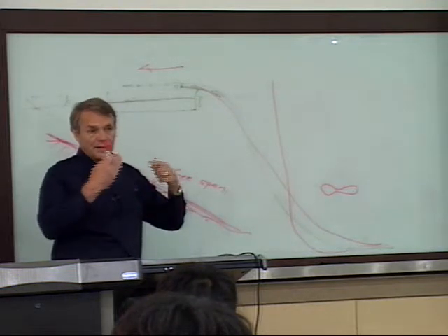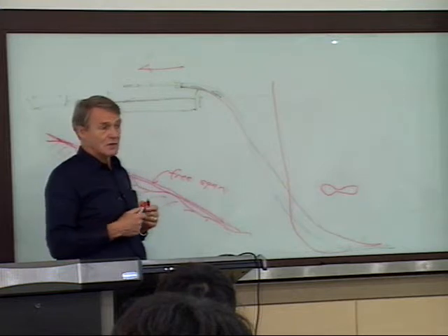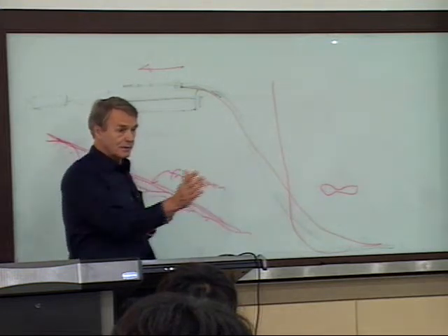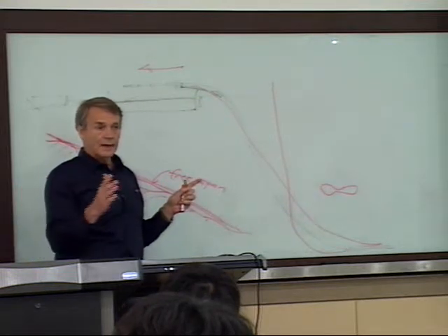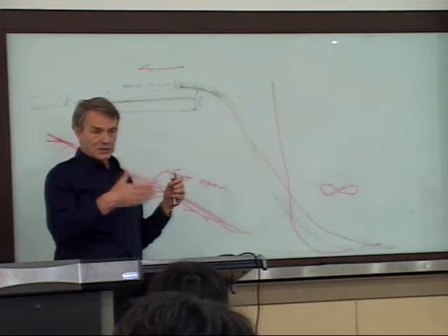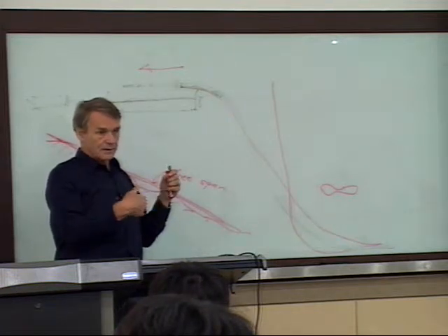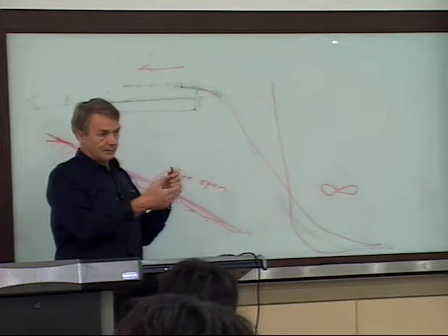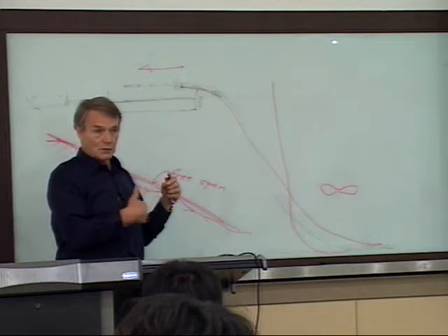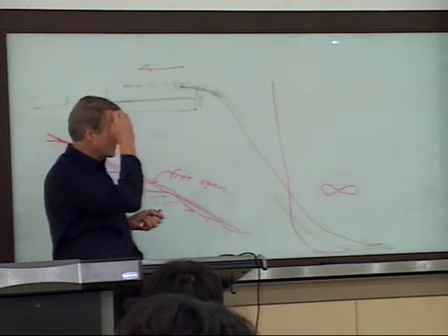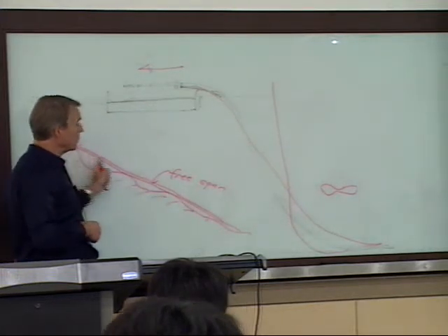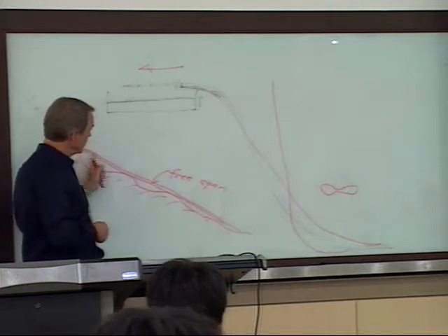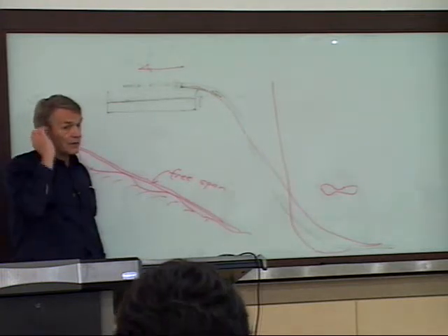Well, of course, you have some bending there, but that's not the main concern. The main concern is when you have current, and let's say you have a long free span of more than 100 meters, and then you can have vortex shedding, the fluid structure interaction, and the pipeline starts vibrating. And then you can have fatigue in the pipeline because of that. So that is one computationally challenging problem with this kind of situation to find out whether it's safe or not.